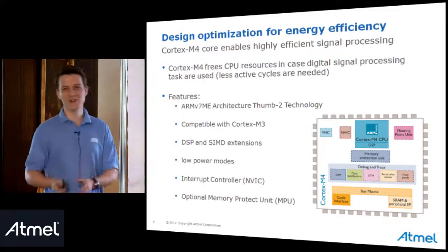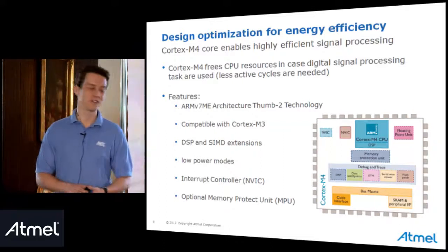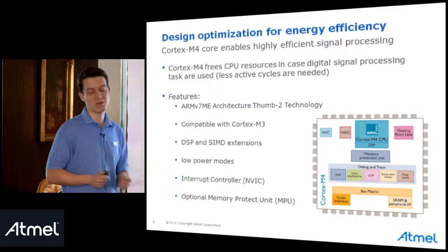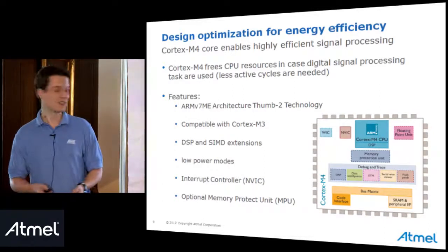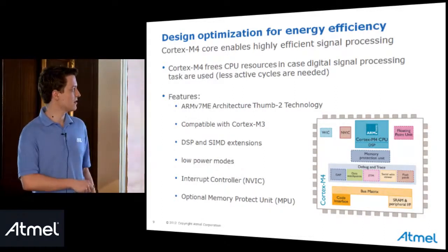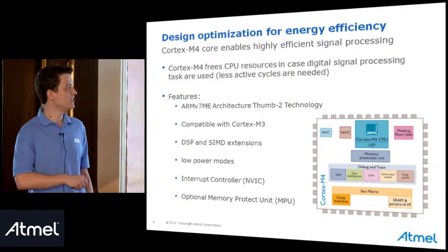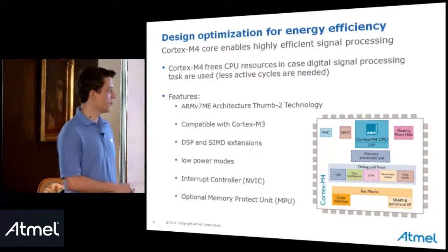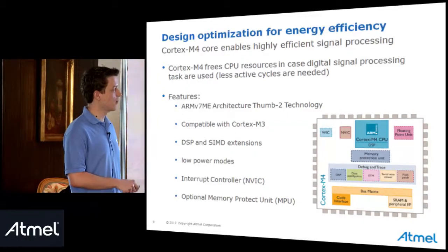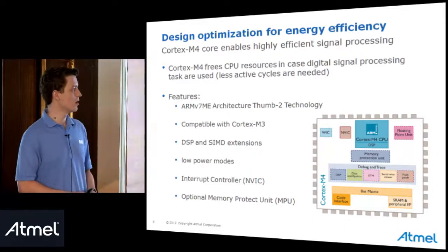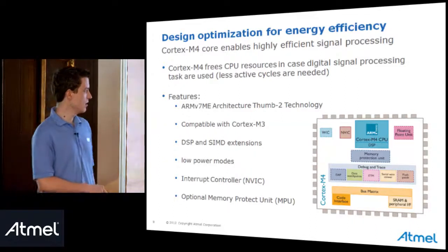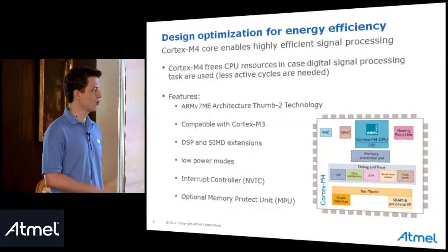So concerning the core, we are using a Cortex-M4 core. This core has mainly been designed for power efficiency. It adds mainly digital signal processing compared to Cortex-M3. It's based on Harvard architecture, the ARMv7-ME, which uses the Thumb-2 technology and Thumb-2 instructions. So it's compatible with Cortex-M3.